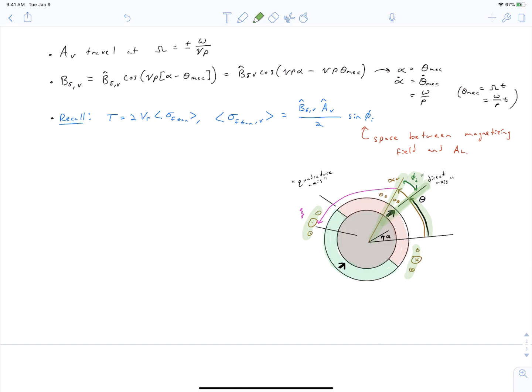And so what we're saying right now is that we can draw this figure right here for every single harmonic. We could construct an equivalent number of poles on our rotor for harmonic 1, 2, 3, 4, 5, 6, whatever, any number. We can draw a rotor with that many poles. And then we've established an expression for our current linkage for that many poles as well. And so we can talk about the distance between the axis of that current linkage and our equivalent rotor.